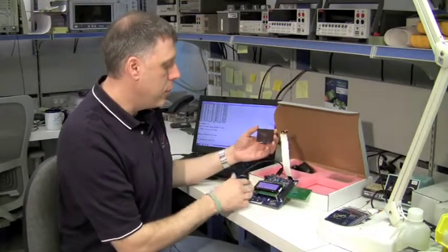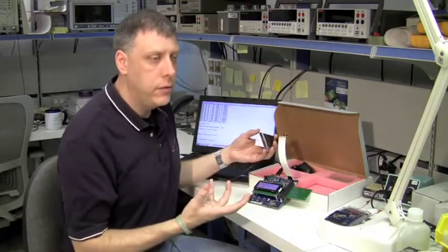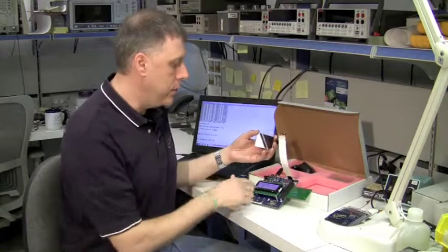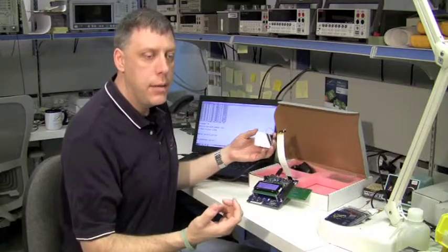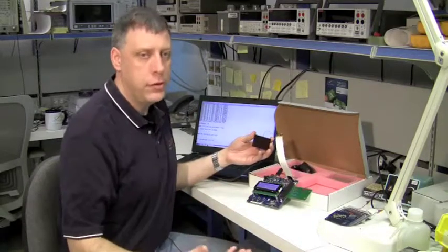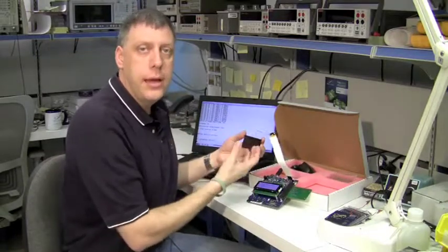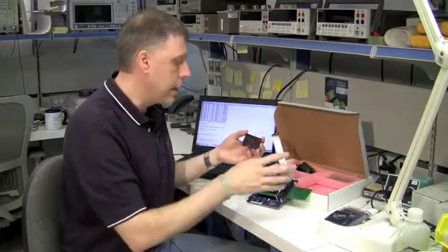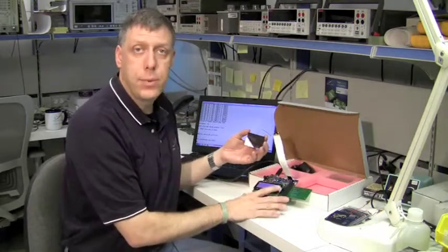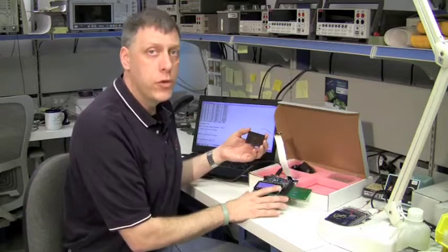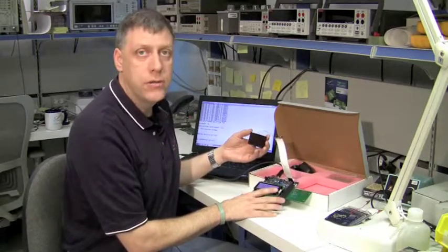Now there's a couple of different modes. You can do bucketed mode where you collect some energy over a long period of time, say into a capacitor, and then you can flip a bit, which will tell the ADP kit to connect the charge source to the MEC for a short period of time to dump that energy. The other method is pass-through, where any energy that you supply to the energy harvester is just directly connected to the MEC and supplied directly to the MEC. The ADP kit has protection in it that will prevent you from overcharging the MEC if the voltage or the current levels go too high from your energy harvester.